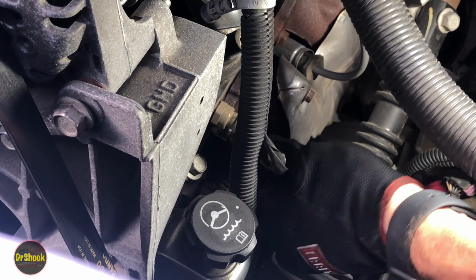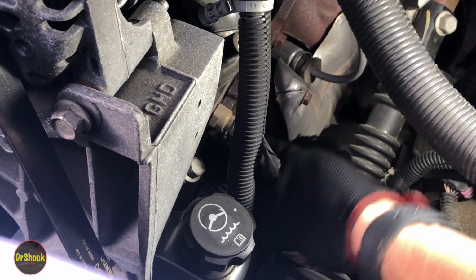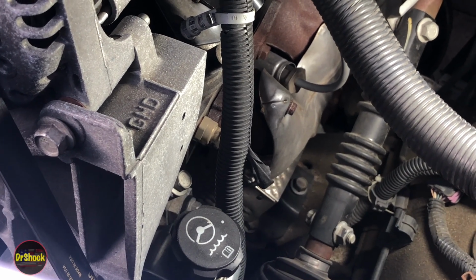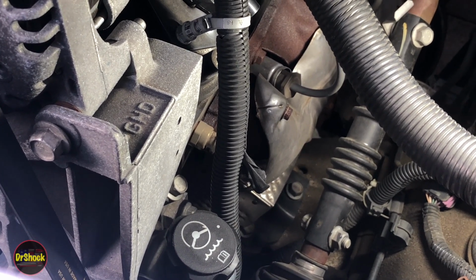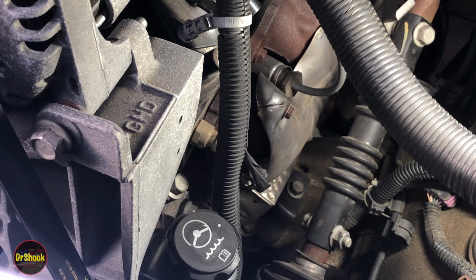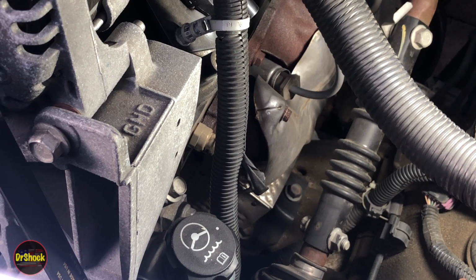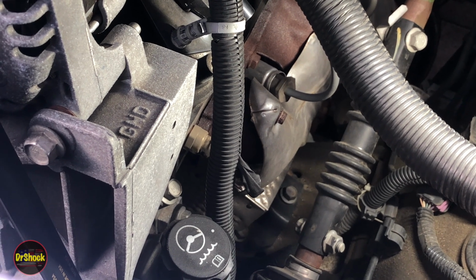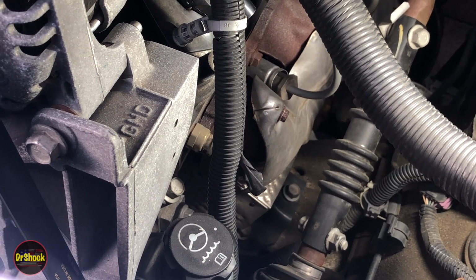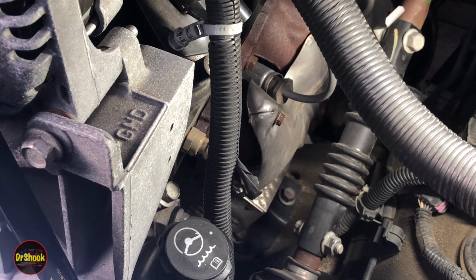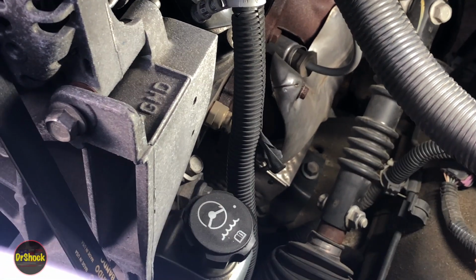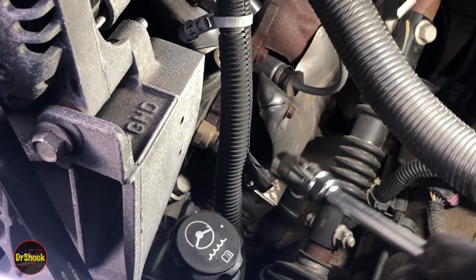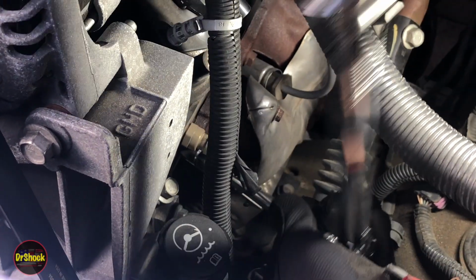And then when I do the torque wrench, we're going to pull this socket off, because we can't use a swivel with a torque wrench. We'll get a bad torque output for that. Grab the torque wrench over here from the tool tray. Set it to 11 foot-pounds. Put that plug wire back on, and we'll see what our Tech 2 has to say.